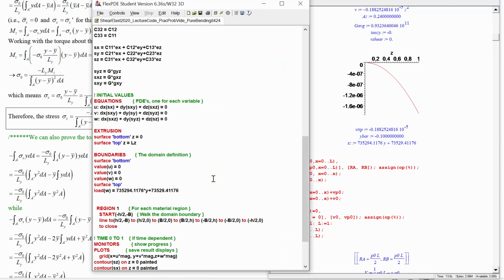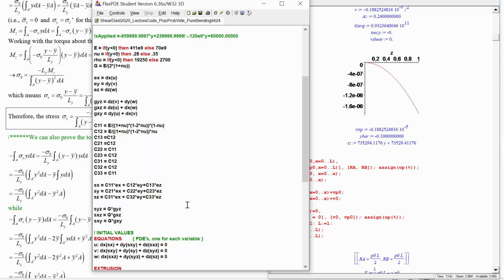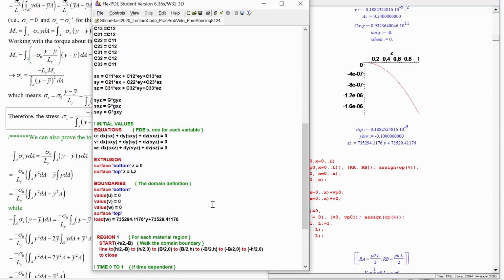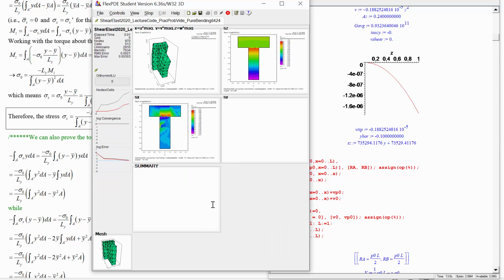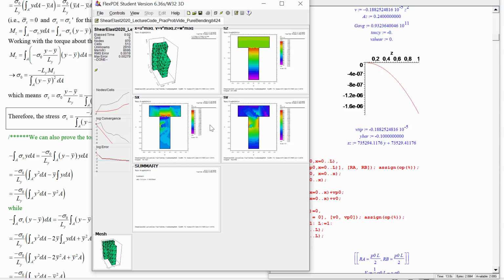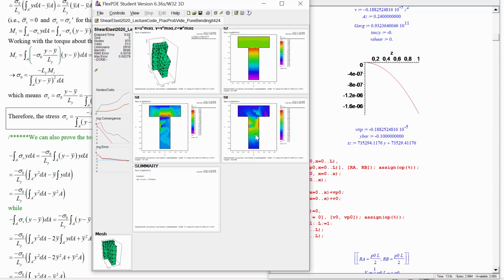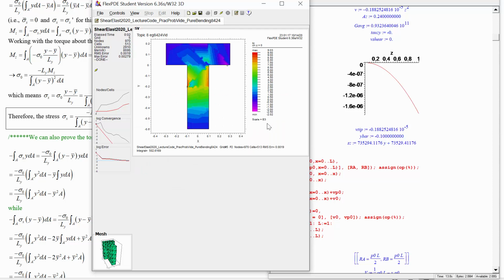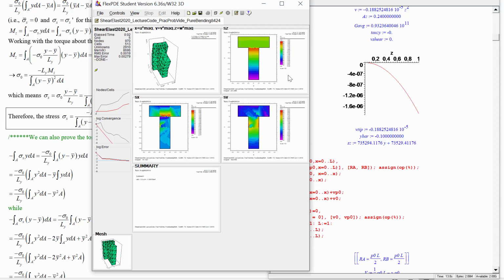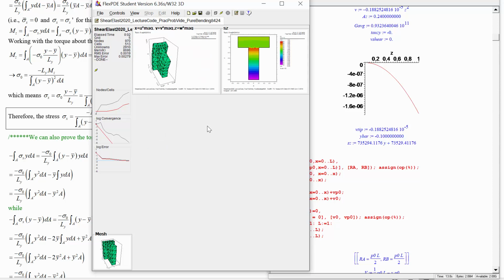Well, we can get rid of it by freeing the surface in those directions. So on the bottom surface here, instead of saying value of U and V are set to 0, let's say, you know what, on that surface, you want to move in X and Y, you go for it. No more stress applied there. So now it's on the scale of E3 instead of E5. At least it's 100 times less. It's not quite no stress necessarily, but that's how it worked out.